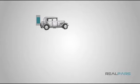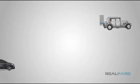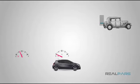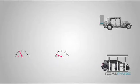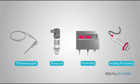At one time, cars had no fuel gauge, and you had to have a reserve tank, a gas can, so that when you ran out, you could get to a fuel station. Now, cars all have fuel gauges, and we will next look at the sensors that make that possible, along with many other measurements that automation requires. An analog sensor is one that converts a variable physical quantity into a signal that the control system can understand, a voltage or current. By physical quantity, we mean temperature, pressure, humidity, distance, and speed.